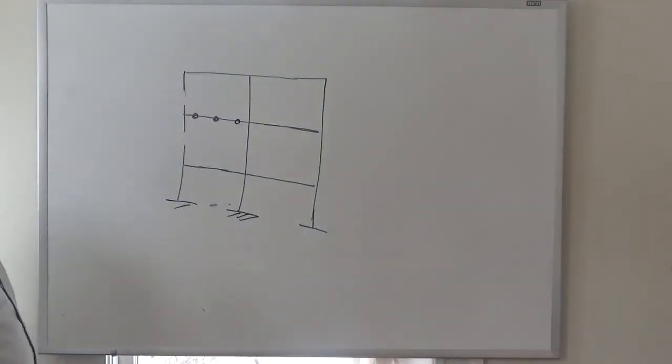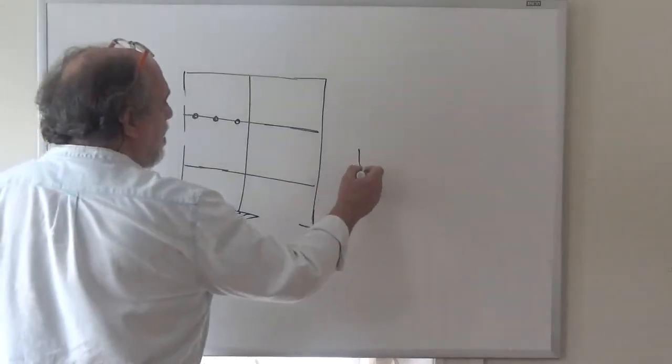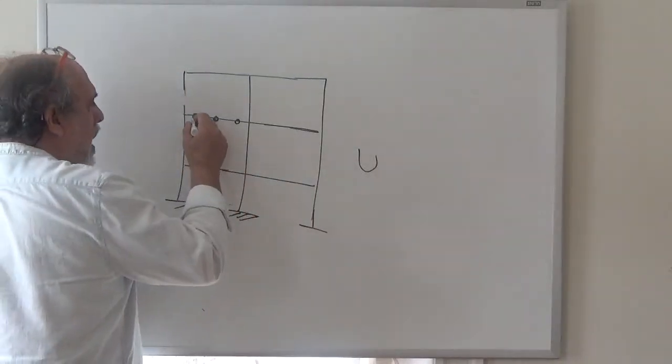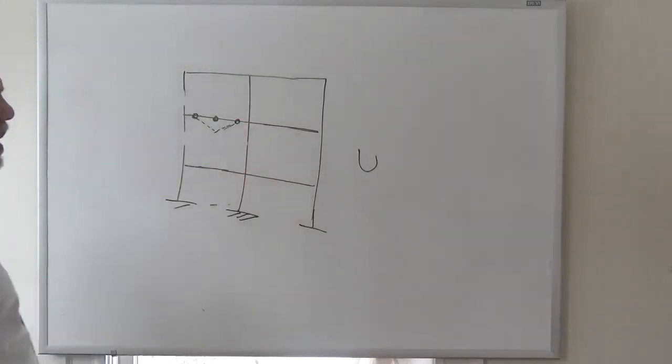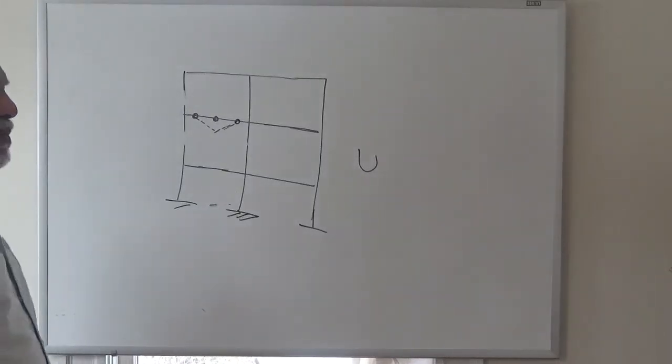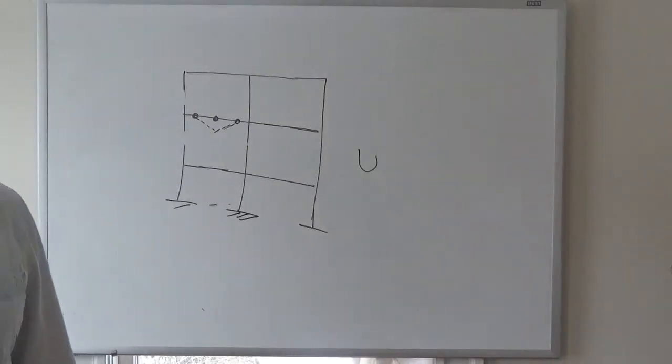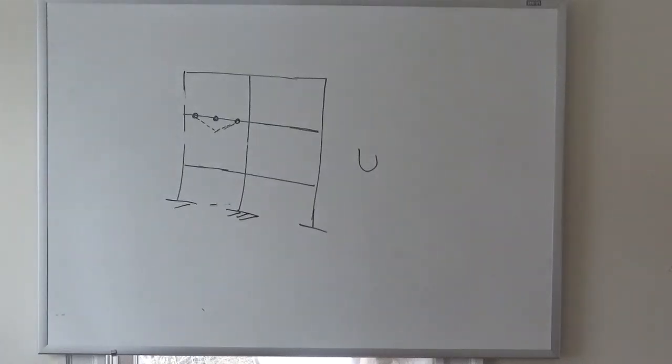You might say, okay, this is now I15. No, that is unstable, because now you have the ability for this part to move down without any restraint, okay? And so the possibility of unstable arrangement is always there, and one should always keep your mind open.